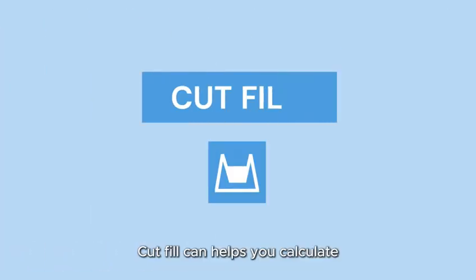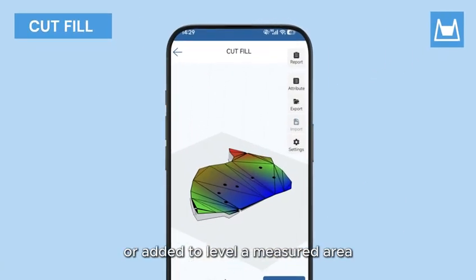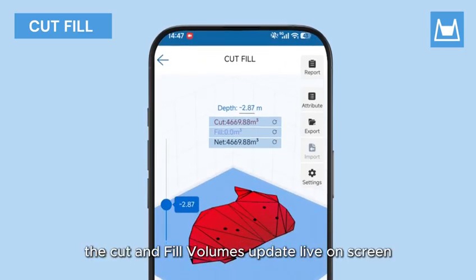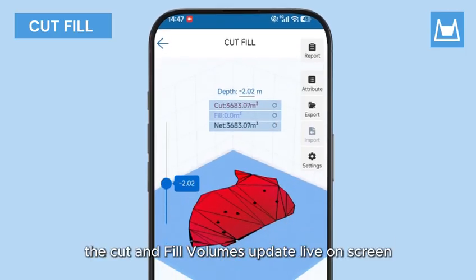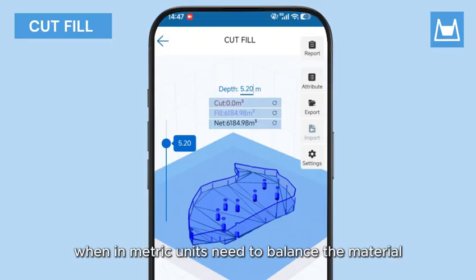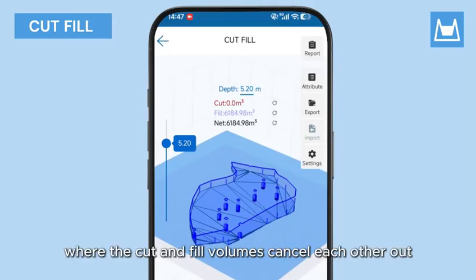Cut Fill can help you calculate how much material needs to be removed or added to level a measured area. You'll see a cutting plane appear, along with 3 key values: cut the material above the plane, fill any space below the plane, and net the total difference. The cut and fill volumes update live on screen. To set an exact level, you can input your value in the depth field. When you need to balance the material, tap the reset icon next to net to find the level where the cut and fill volumes cancel each other out.